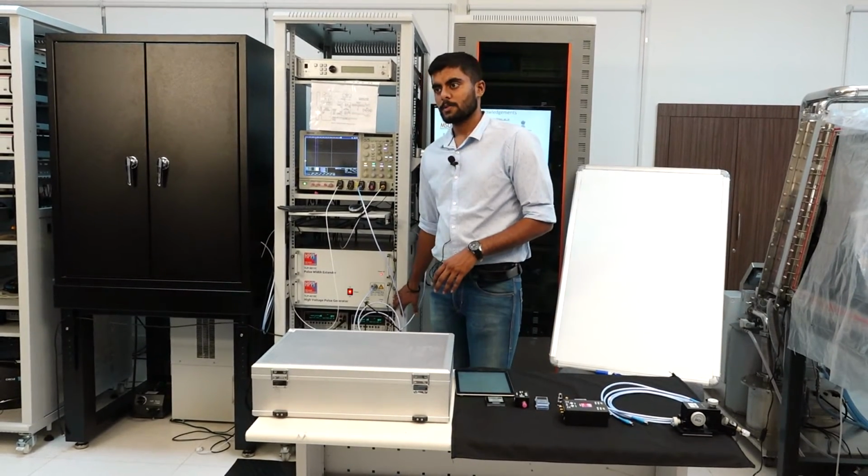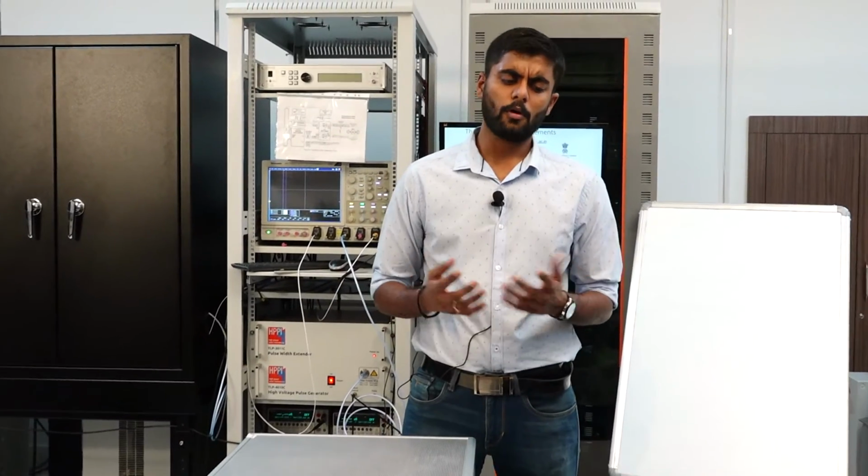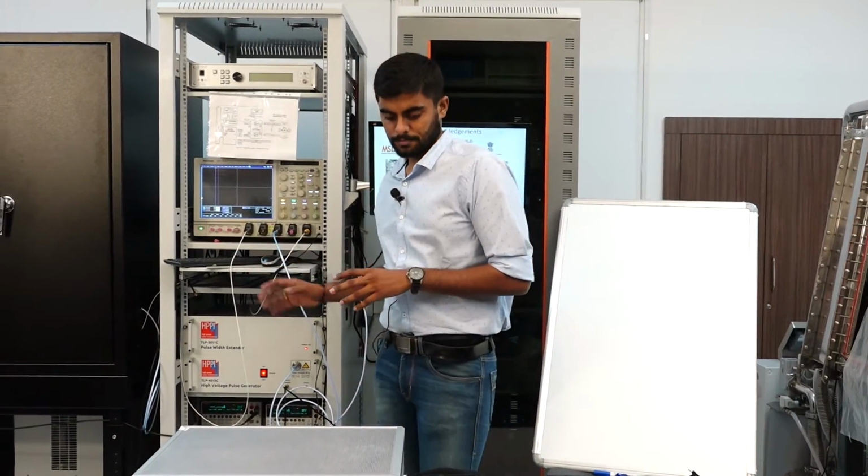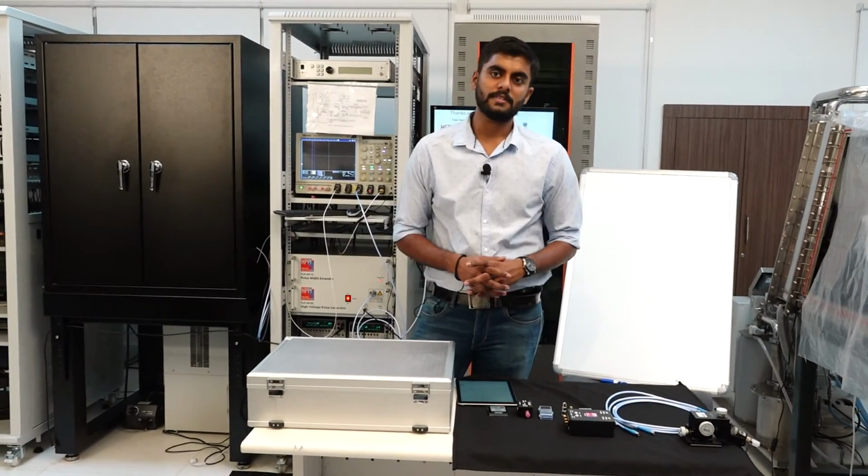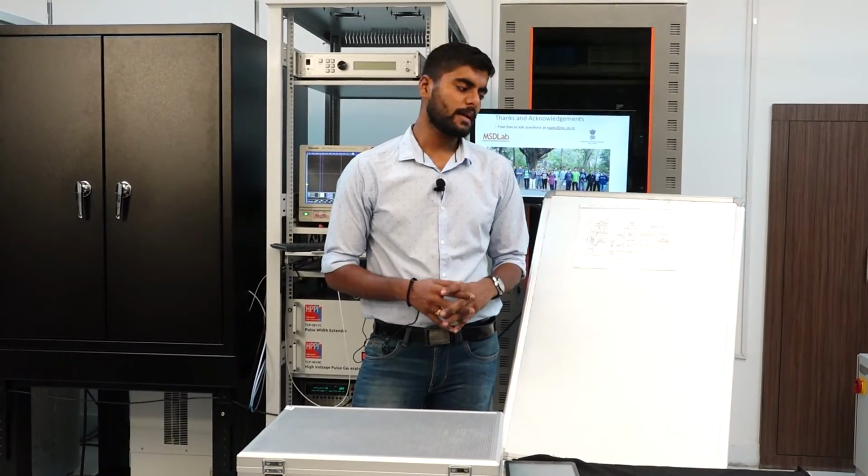And there are a couple of SMUs involved as well. These SMUs are important if you want to apply a DC bias to your device under test while also applying the pulse voltage. So say for example, if I were to keep a gate grounded during the measurement and I were to apply these pulses at the drain contact, I can then connect the whole assembly in one shot by connecting the gate to an SMU, the source and drain to the TLP setup here, and then I'll measure everything through this oscilloscope. So those are some of the major components of a TLP setup. Now what I'll do is I'll talk more about the whole setup. I'll tell you what are the different things involved and what are the different connections involved in the whole TLP setup.